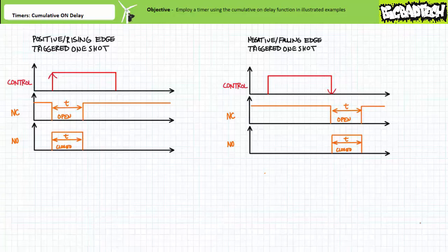One-shots can be used to assert an output for a desired time period following the energized or de-energized transition of another device. One-shots are particularly interesting because manufacturers occasionally include a slew of handy features, including resets and retriggerable versus non-retriggerable one-shots. Note, for this general purpose orientation, I've purposely simplified the timing diagram for rising and falling edge one-shots.